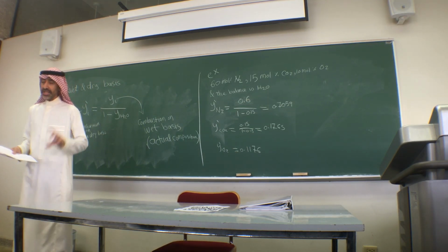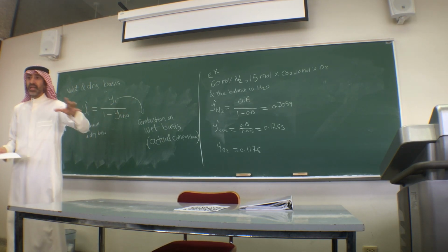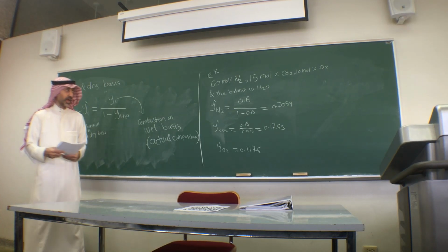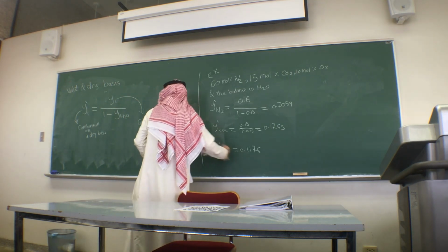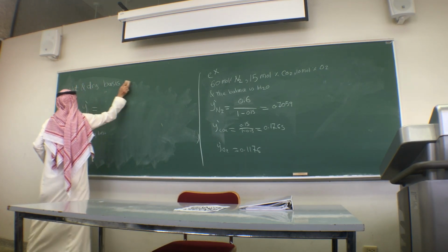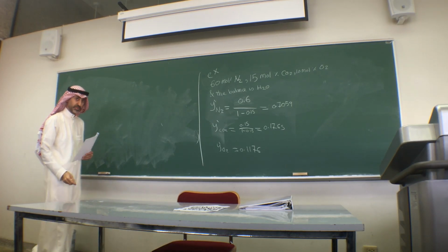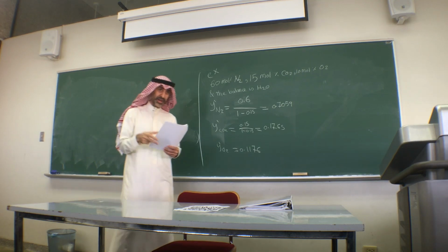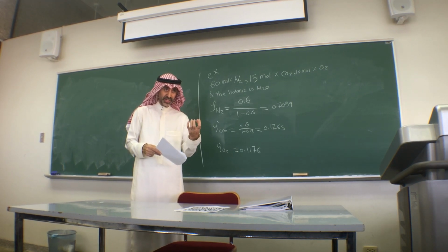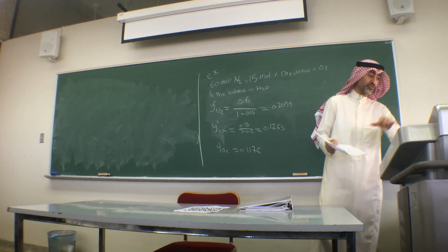As easy as this. And sometimes you will be asked vice versa: you have the fraction on a dry basis and must find it on a wet basis. Is that clear? This is the second important thing. I'm just giving you the concept we will need to solve any combustion problem. Doctor, yes. In the reverse case, he has to tell you how much water there is. He will give you the composition on a dry basis and tell you that you have this amount of water, so you have to consider it.